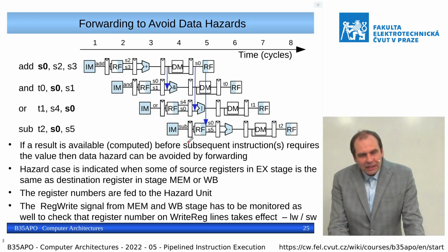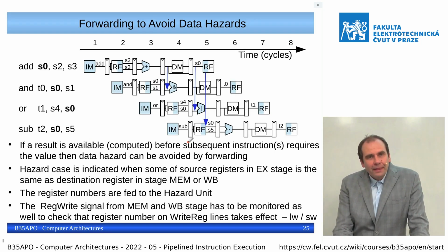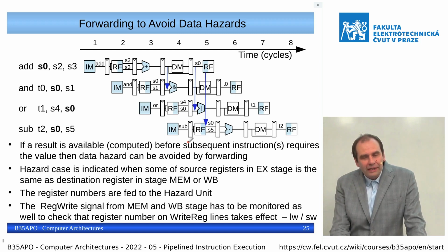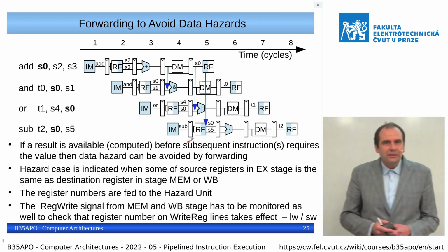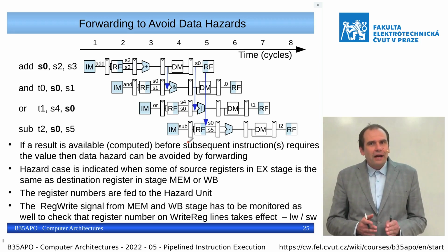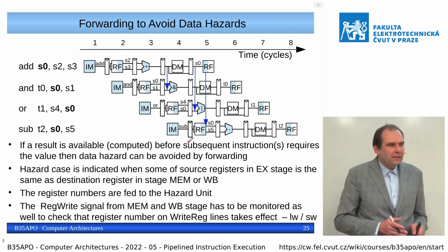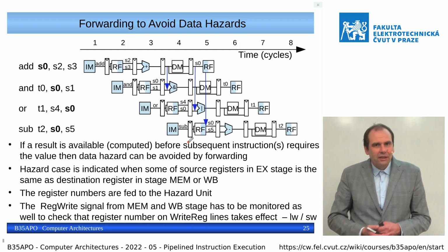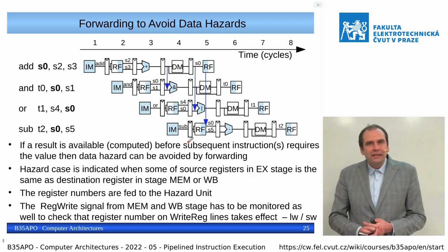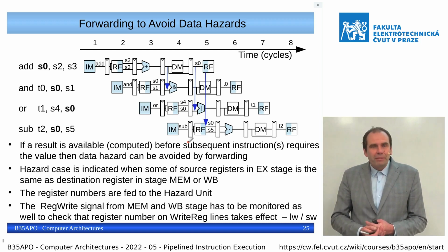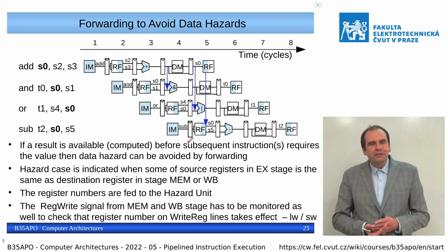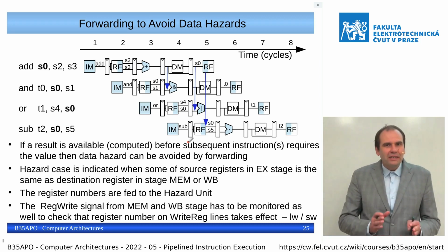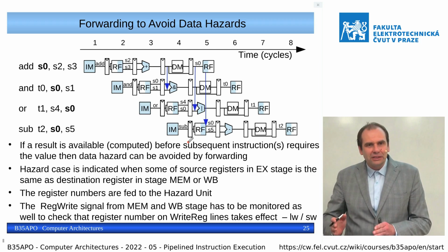But it has a disadvantage. If we use this stall mechanism, then if there are many interdependent operations, we need to wait 2 clock cycles after each operation till we have a result. We have hopefully sped up the processor by dividing execution into pipeline stages.